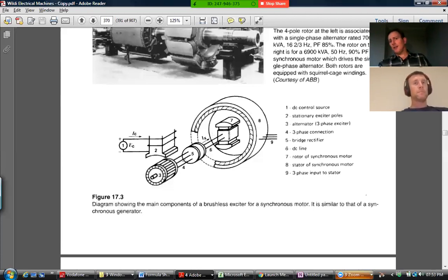Okay, so there's actually a mini generator in here, but that's got to get power from somewhere. Where does it come from? It comes from the shaft. Where does the shaft get its power from? It's actually coming from the grid. So there's an electromagnetic field, obviously, interfacing between the stator and the rotor that's pushing this rotor around. Whereas the turbine was kind of trying to drag it ahead of the rotor, now the rotor is pushing this thing around, or pushing, pulling, doesn't really matter.